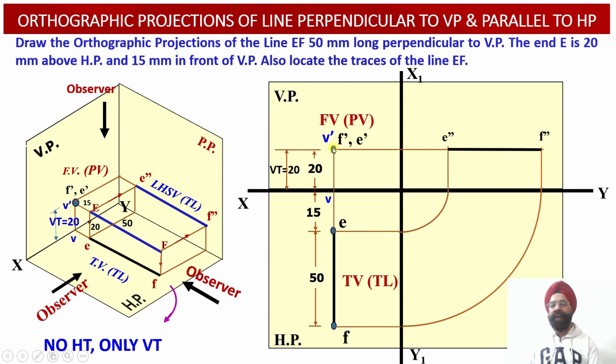Similarly, wherever the horizontal locus line emerging from the point F dash intersects with the vertical projector line drawn corresponding to the point F, this is the vertical projector line drawn corresponding to the point F. Why? Because you can see from point F we have drawn the horizontal locus line.